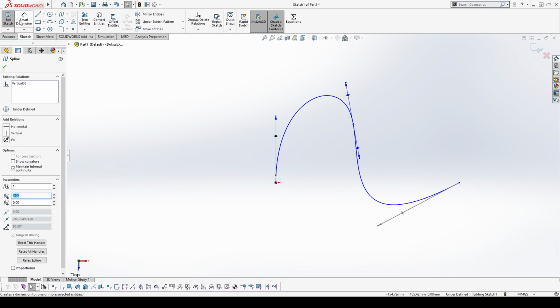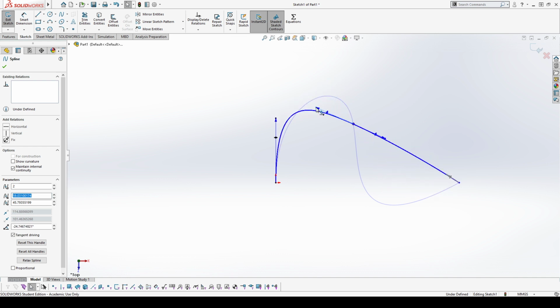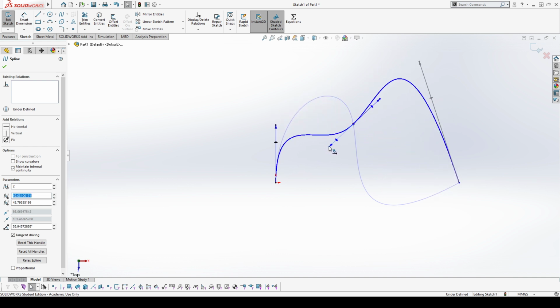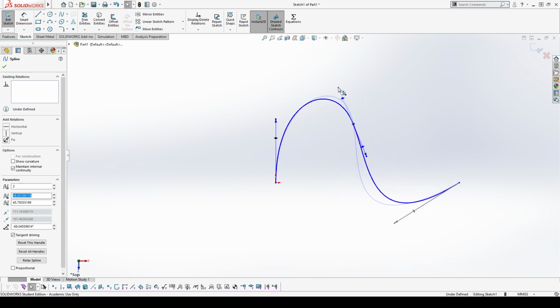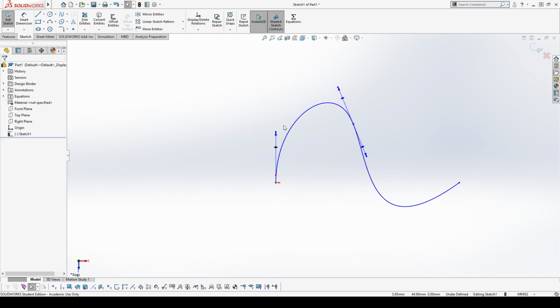You can dimension these. It's kind of wacky. I personally haven't figured out exactly what those dimensions mean. I'm pretty sure it's just the curvature value at that point. But again, just by moving around these points, I can get all these organic interpolated shapes. It's just kind of guessing at what's there by moving around these spline handles. And it boils down to, if you have a particular shape you're trying to get at, you're just going to be fiddling around with these spline points until you get it just right.